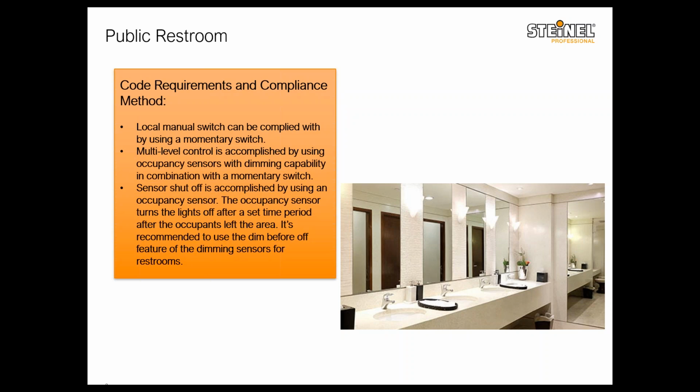Just to remember one little thing: the total time delay for the two timers, the occupancy and the dim before off timer, is 30 minutes. So you can't set both of them to 30 minutes and expect the lights to stay on for 1 hour.